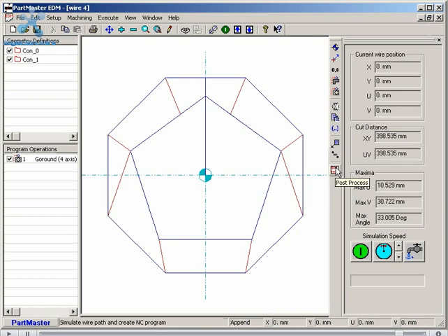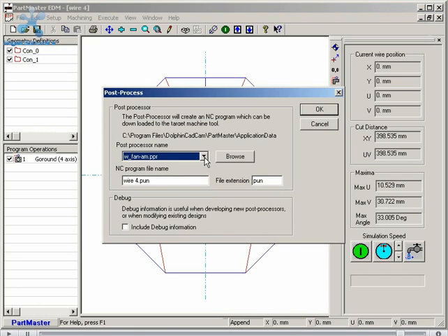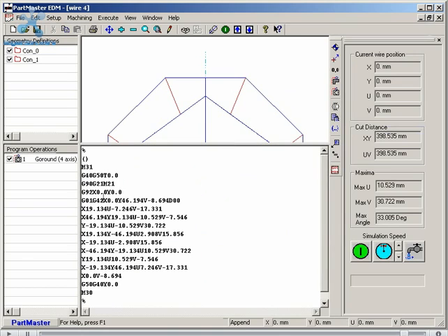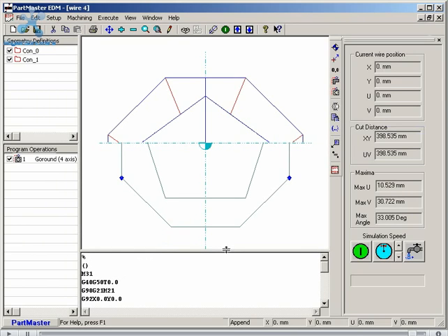When you come to post-process that, of course, what you'll end up with depends on your machine tool and the post-processor, but in general you're going to get XY and UV commands which will produce that shape. That ends this tutorial concerning 4-axis cutting.